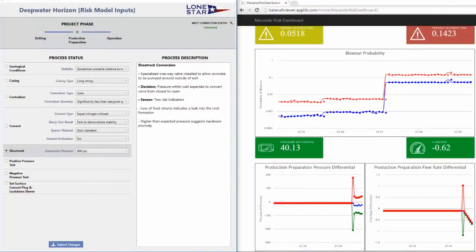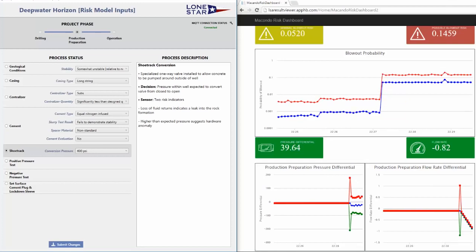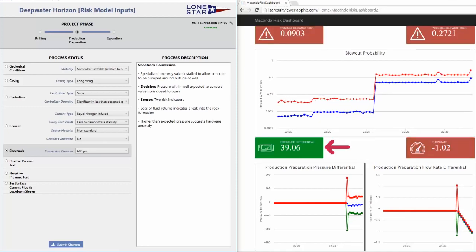The design expectation was that 600 psi would establish cement flow into the well. Even when pumping fluid at 1800 psi into the well, the crew was unable to establish cement flow. At that point, the rig team decided to increase the pump pressure in discrete increments, hoping eventually to dislodge the autofill tube. On their 9th attempt, mud finally began to flow.